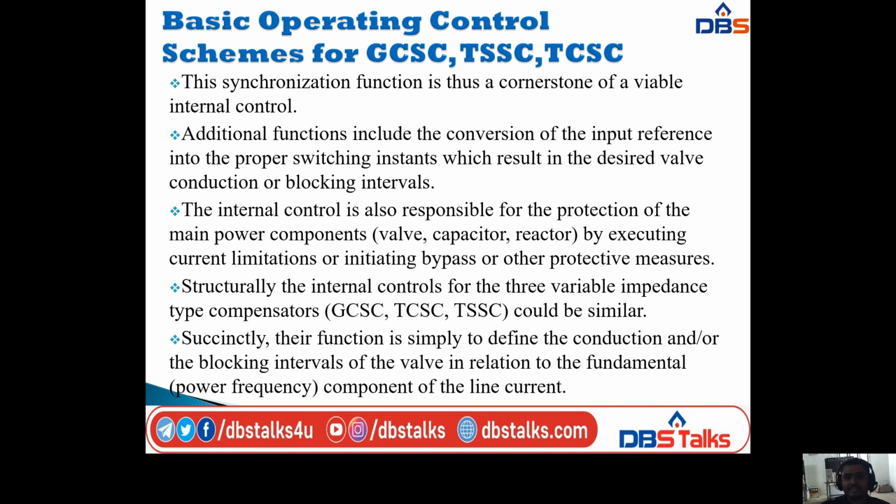So here we are using additional functions. These additional functions include the conversion of the input reference into the proper switching instants, which results in the desired valve conduction or blocking intervals. Here I will show the internal control schemes of these GCSC, TSSC and TCSC. The internal control is also responsible for the protection of the main power components, that is valve, capacitor, reactor, by executing current limitations or initiating bypass or other protective measures.